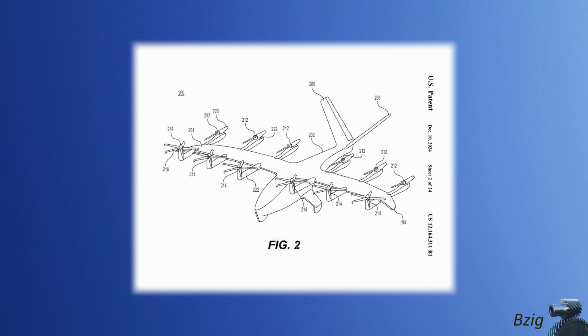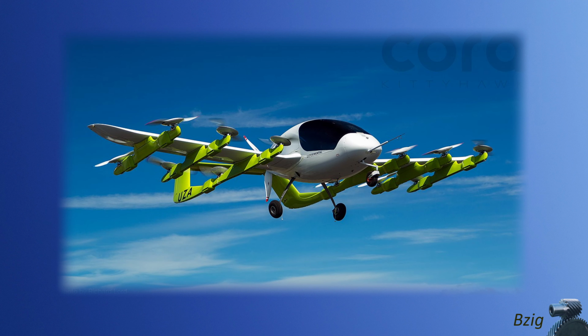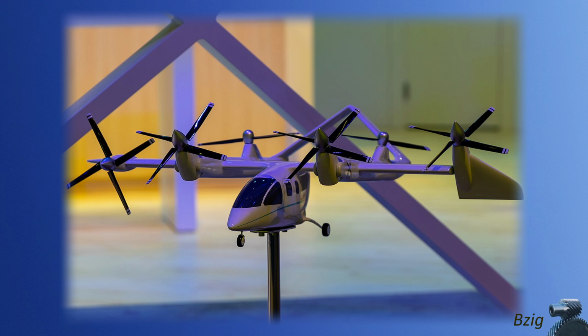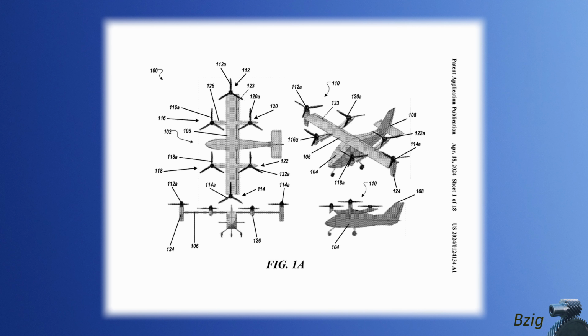The 21st century may be challenging this core design assumption of these twin-engine tilt rotors. Some of the distributed electric propulsion designs forego the mechanical safety advantage of connected rotors by adding motor redundancy to the design. One design concept is that when one electric motor fails, they can intentionally mirror that failure to the other side in order to retain symmetric thrust.